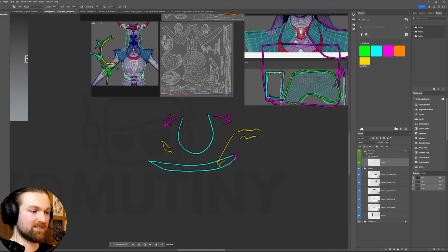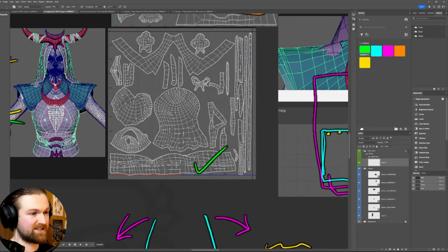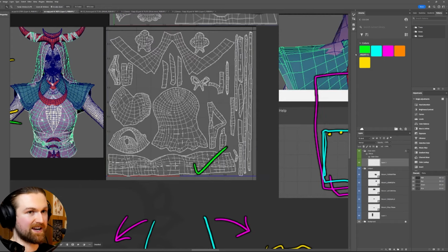That's not such an enhanced level of distortion, and we get a lot of benefits in being able to fit it on a UV. So you can see where you've done that already. You've basically straightened up these UV islands, and as a result the UV is becoming more efficient, so better for the game, and we're also getting some more resolution out. So as to your question, you had a really good question, and that was basically when you start to edit a 3D model and you already have the unwrap.